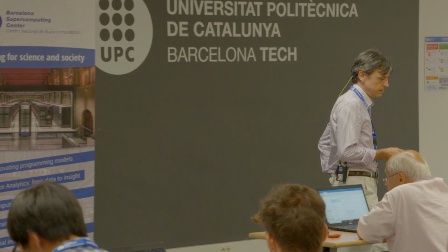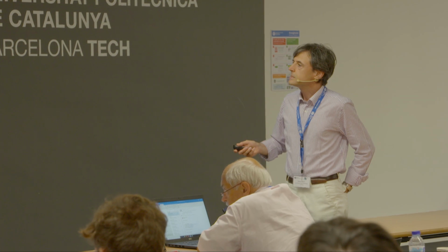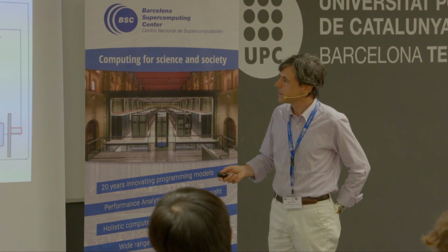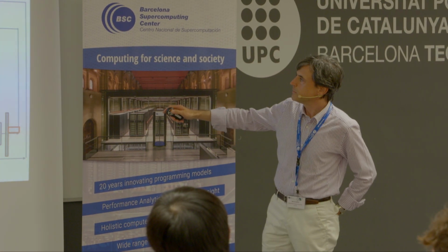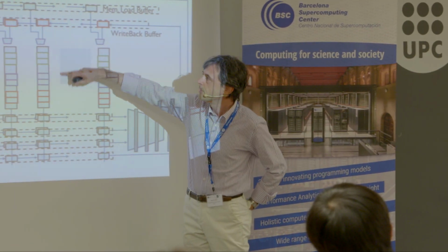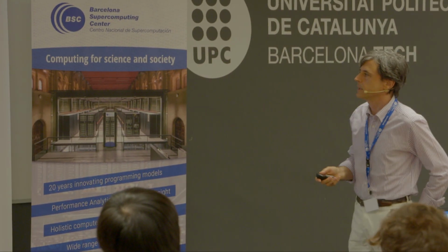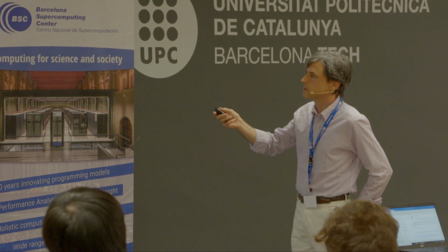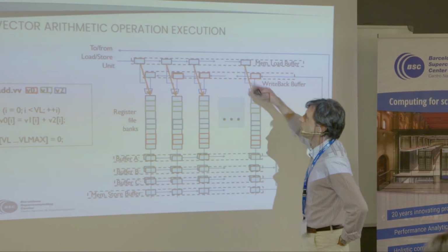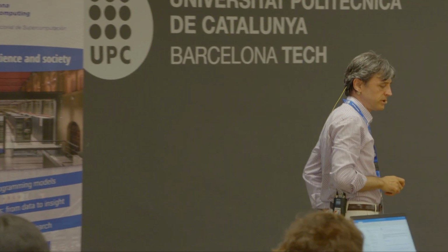When, of course, after an initial startup time. You may say, okay, why this particular organization? Because, for example, take a look at this intermediate point. While we were still producing some result here, the register file is idle, meaning that we are not reading or writing anything there. And so we can use this time slot, for example, for loading data coming from memory, while we are performing a vector arithmetic operation.